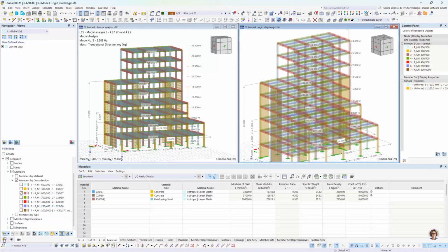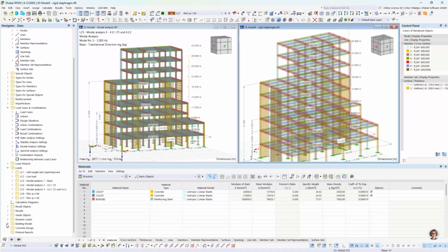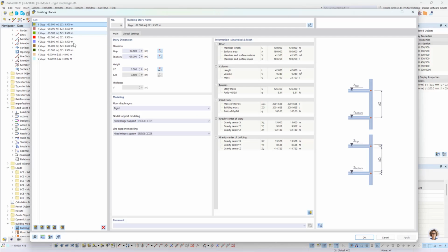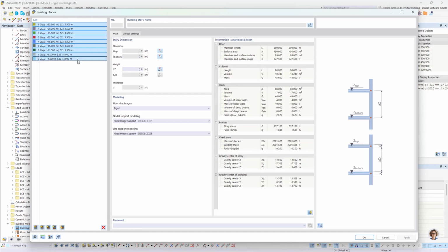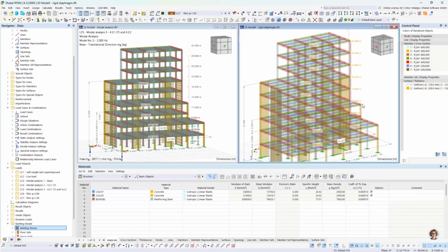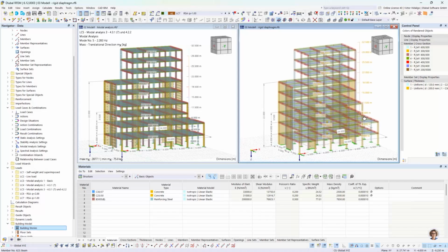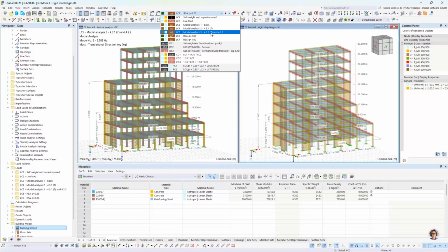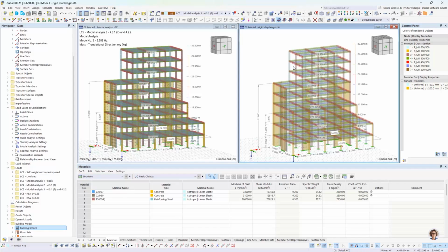So in the first place, I want to show you the definition in the building model add-on. In this case, I have the same definition, but I selected all stories and selected the floor diaphragm as rigid. I already ran the analysis just to save time, and in the same way I'm gonna look for the results of the modal analysis iteration number 3.